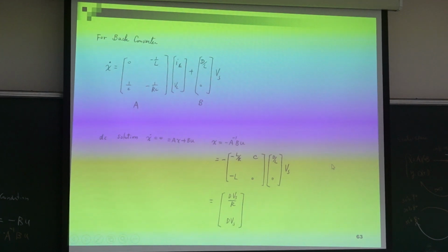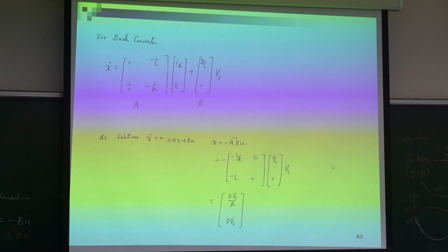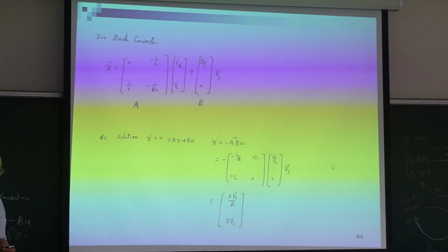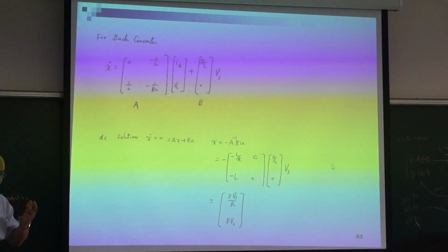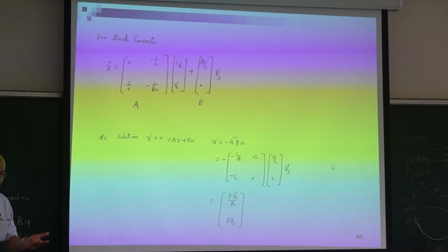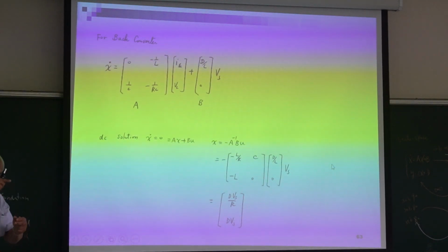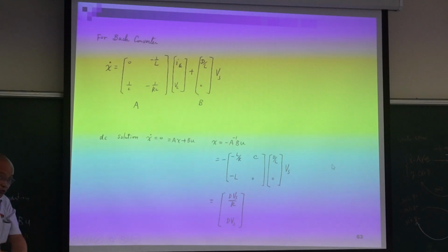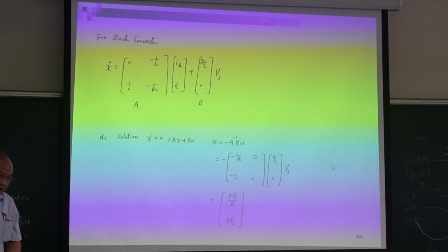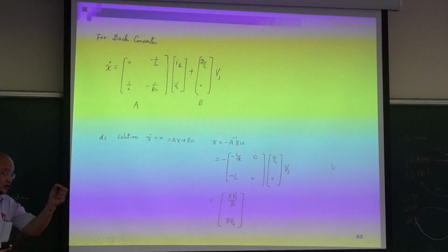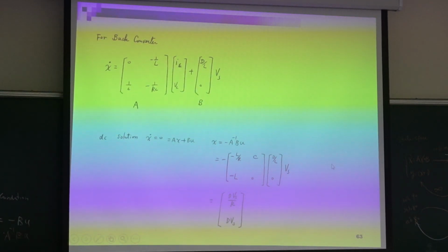How about the inductor current? So now I ask you, what is the inductor current? Inductor current includes two parts. One is IC, one is IR, right? So inductor current, IC and IR. What is the average of IC? Anybody has any idea? What is the average of IC? If IC is 1 ampere, then the voltage increases to infinity. If IC is minus 1 ampere, then the voltage decreases to 0. So what is the average of IC? 0. So the average here is 0.